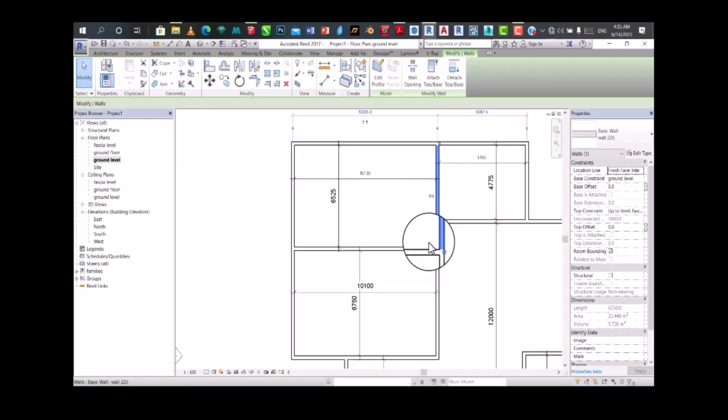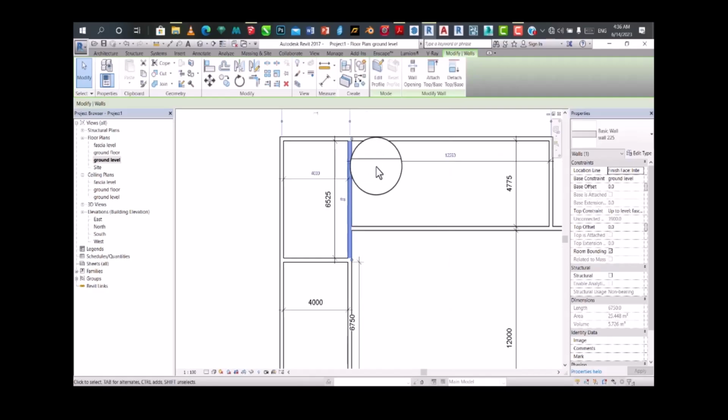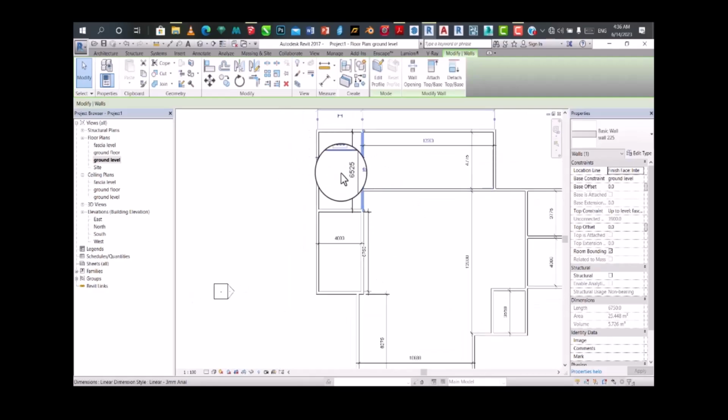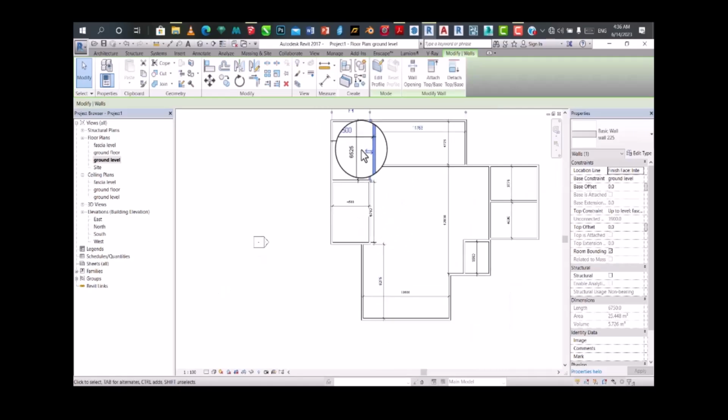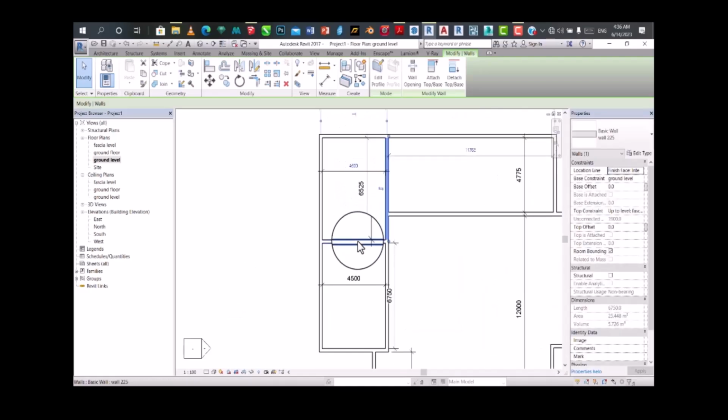In my case, I would like to move this wall, so I can edit this to maybe, let me give it 4 meters. Let me make 4.5 actually, because 4 is a little bit small. So 4.5 meters. Okay. This is actually big. Now I want this one to go up, not this one coming down.